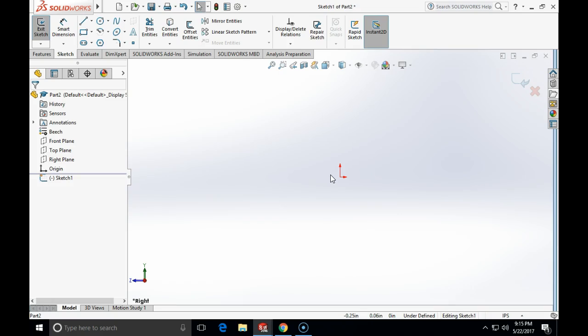Now, looking at this part with those two holes, obviously I will not put the holes in the primary sketch. I'm going to put them as placed features, as holes. However, those stubs at the bottom, which allow this part to be inserted into the base part which you previously created, we are going to do a different way. We are going to do it with the intersections of lines from different rectangles, and then when we extrude, we are going to choose which closed areas we want to be extruded.